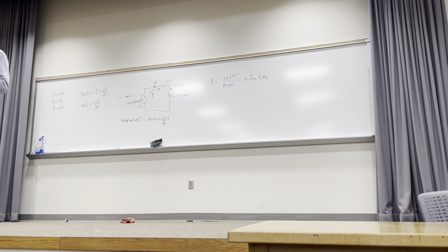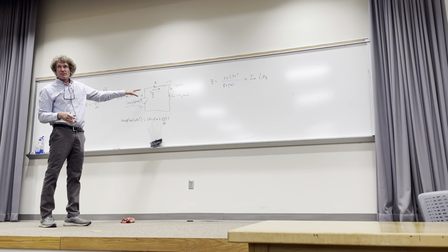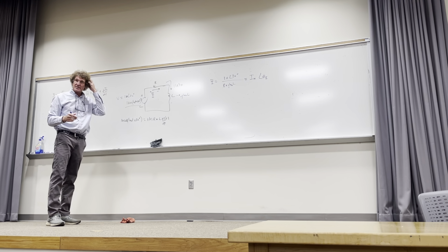Remember, that's a phasor. Remember this when you go for a job interview. If anybody gives you one of these kinds of problems, don't do it with differential equations. Go right to the phasor domain the minute you see this cosine or sine of omega naught t in there.